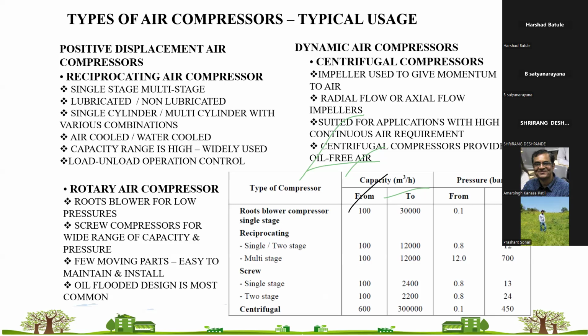If you don't have a water cooled circuit in your entire factory, and the supplier is quoting for water cooled, you need to buy another cooling tower for that. That is an additional expense, because it will require soft water and all these things. So we'll be selecting an air cooled compressor. So that is one of our multiple selection criteria.